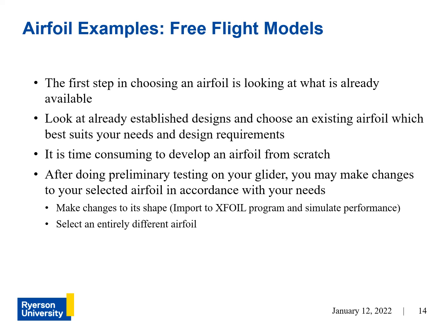Now, after you've found the airfoil that you think is the most relevant to you, after doing your preliminary testing, you can make changes to your airfoil in accordance to the performance that you want. So you can change its shape, and if you really want to get fancy, you can import your airfoil into a program called Xfoil and simulate its performance. Or you can select an entirely different airfoil.